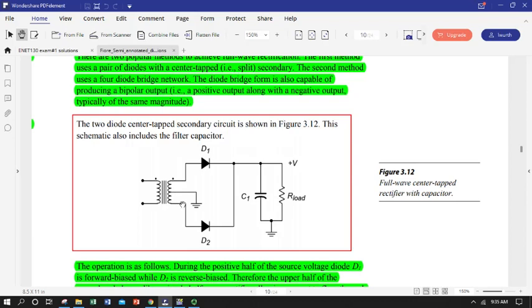And rather than just having the positive end polarity effectively going with the forward half cycle, and then the negative, we've put a grounding point, a center point, so we have another tap. Theoretically this could go out to another circuit, but from the point of view of the rectifier we've grounded the center tap.